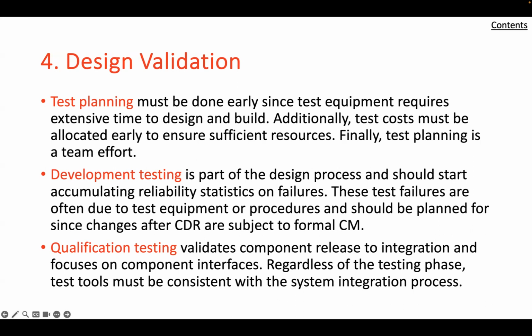At this stage of component engineering, the tools that are to be used in production are seldom available for use, so the initial fabrication must be carried out using manually operated machines and hand assembly. It's important, however, that a realistic experimental replica of the fabrication process be employed for any component parts that are to be built using unconventional manufacturing processes. This is essential to ensure that the transition to production tooling will not invalidate the results of the prototyping process.